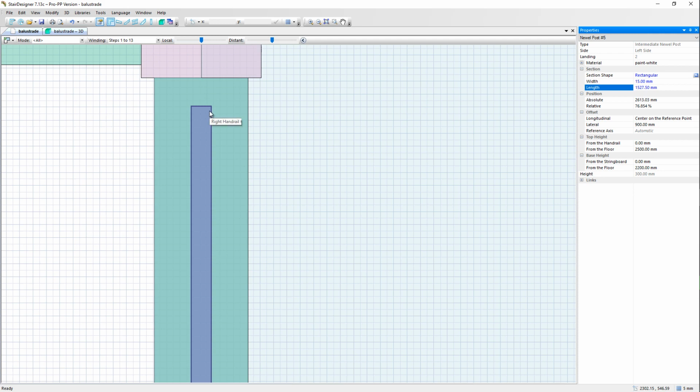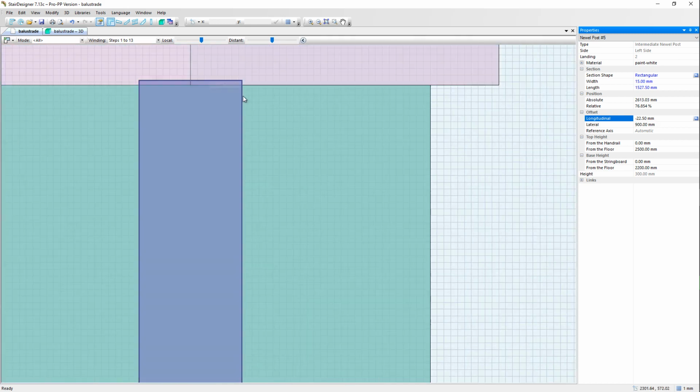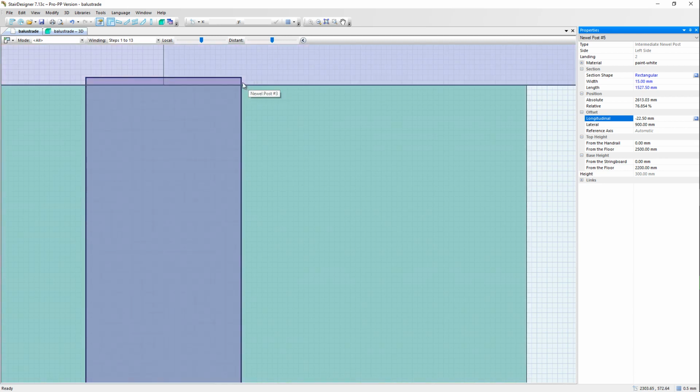the shift. It's about 1, 2, 3, 4.5 squares here. 4.5 squares would be around 22 millimeter. So we are going to take the longitudinal, put it to other, and put some 22.5 millimeter. Going the wrong side, then you put a minus in front. And now you can go check further to see how much it needs to come back. It would be around 0.8 millimeter, so 2170 somewhere.